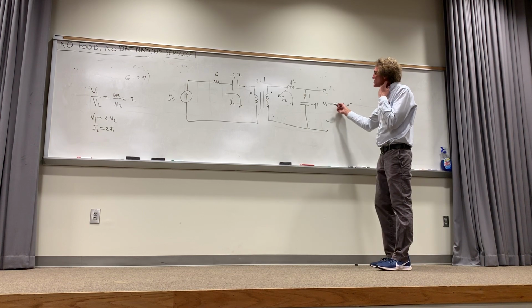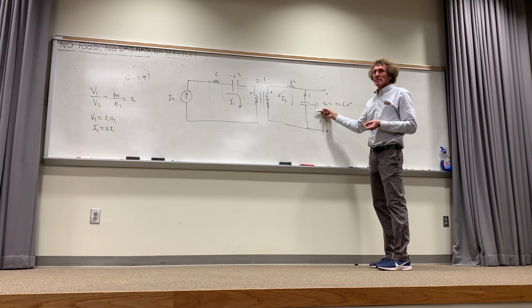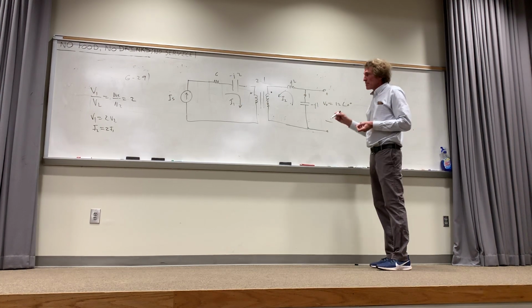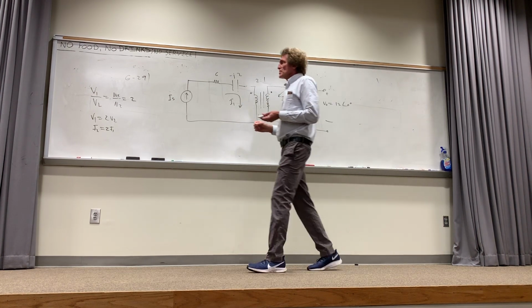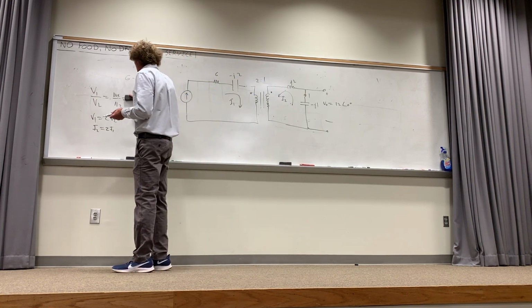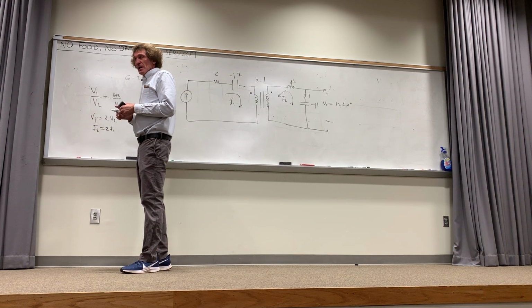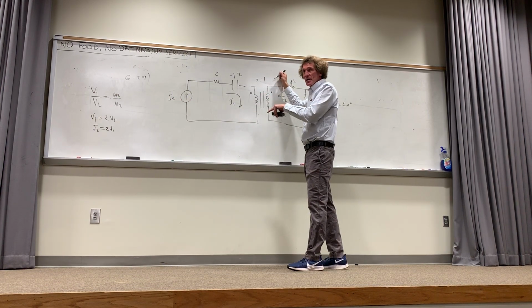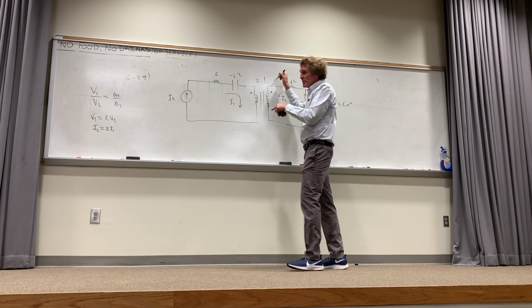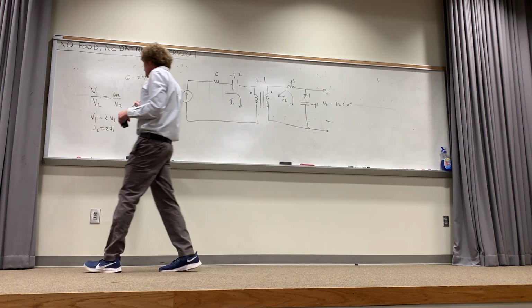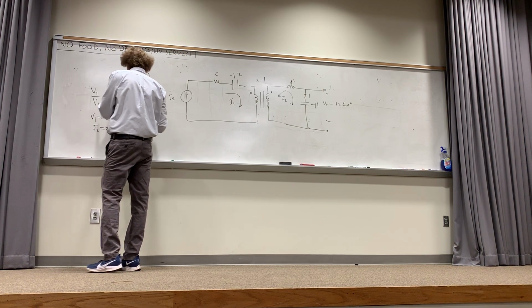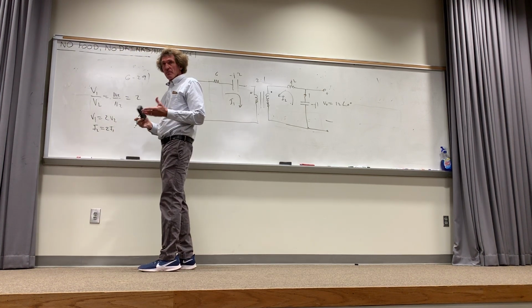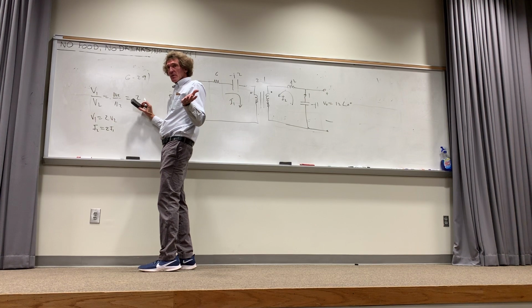If I have a voltage over an impedance, is that V1 over V2? When you look at this, what does turns ratio mean? Normally it's N1 over N2, right? Now look at this. He says there's 2 times as many turns in the primary as there is in the secondary. So N1 over N2 would be 2 to 1, or 2, right? All right, that means 2V2 is V1. Just multiply by V2.